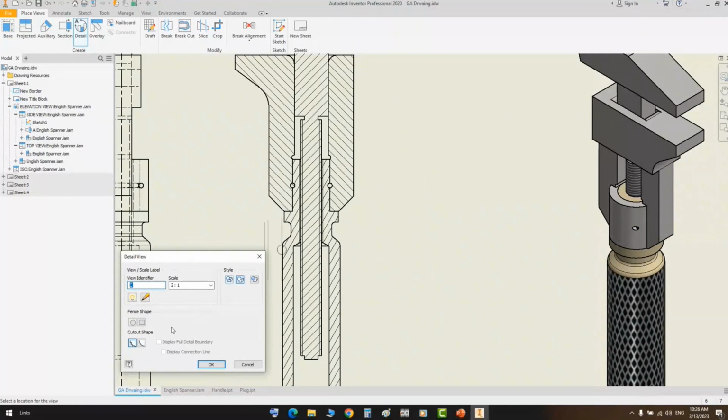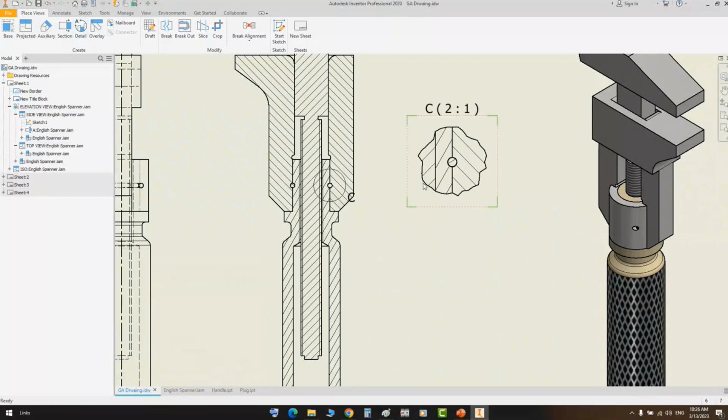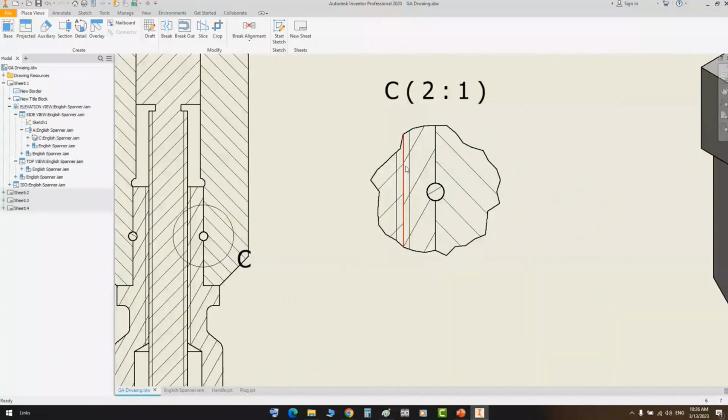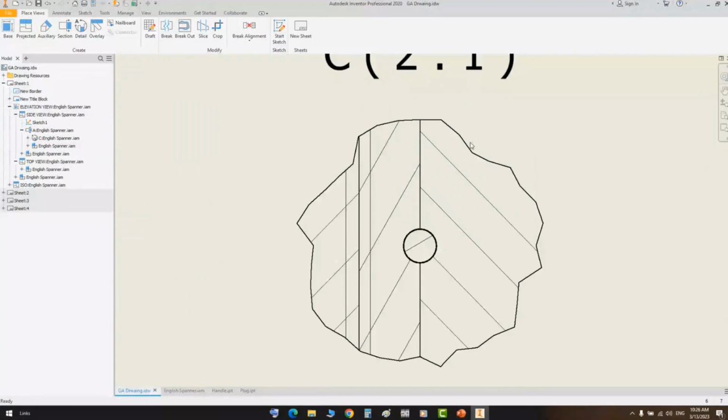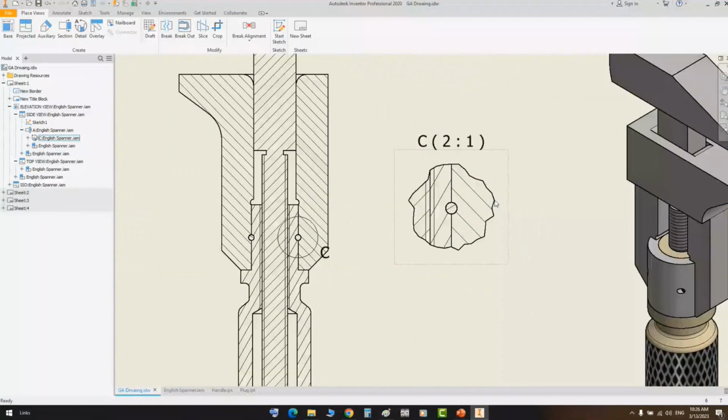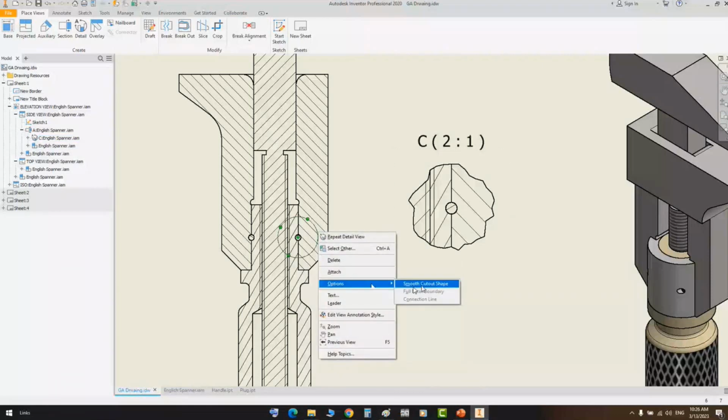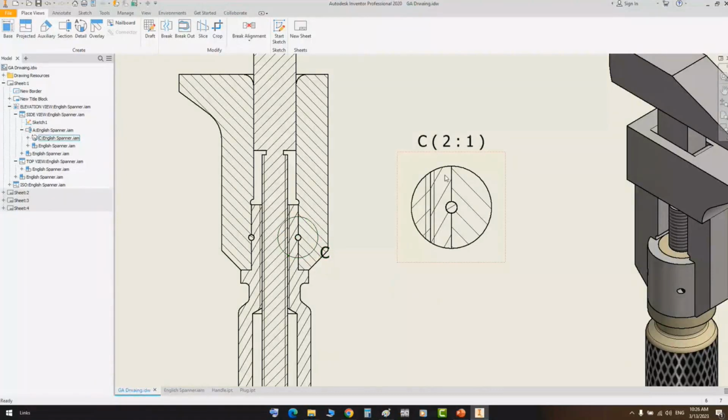Define the scale of the view, and from here, if you select this option, which is set cut edge, you can get the sketch cut out as a rough cut-out surface like that, or you can modify that by making it a smooth cut-out shape. So the cut will be with smooth edges.